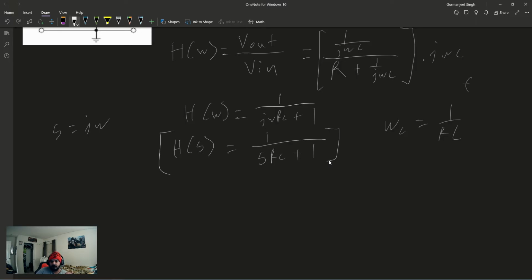but our frequency that we chose previously, our fc, was 5 kilohertz, I'm pretty sure. Yeah, it was 5 kilohertz, so we have to convert this. All we have to do is multiply by 2 pi. So 2 pi fc would essentially be equal to 1 over RC. We also know our R as well. Remember, we set our R equal to 1 kilo ohm.